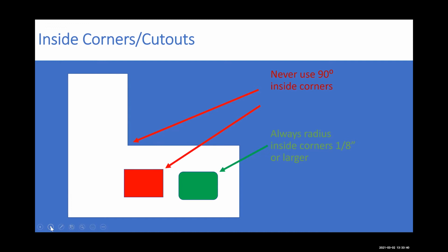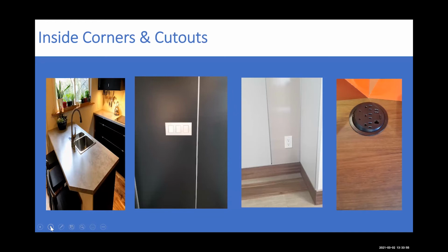Unfortunately, sometimes mill workers do not control the environment, because sometimes an electrician will come on the site and do the cutout for the duplex outlets. The next slide will show us where you properly radius the corners, so you don't have those stress fractures.